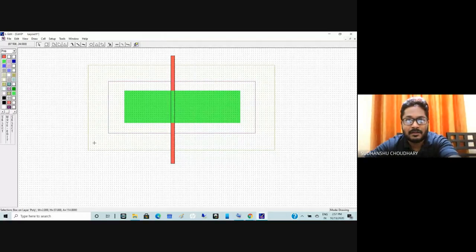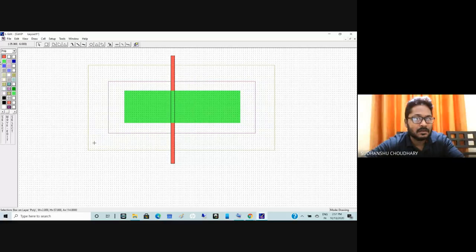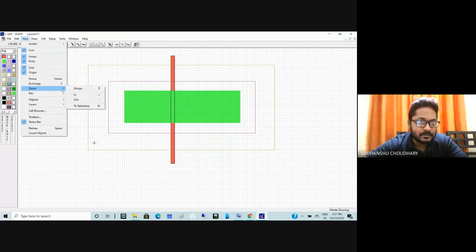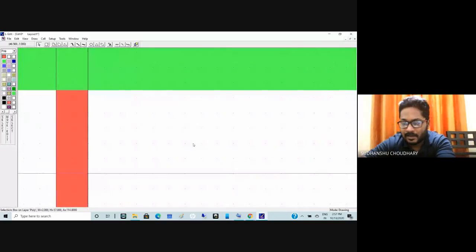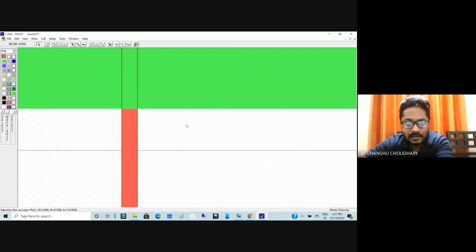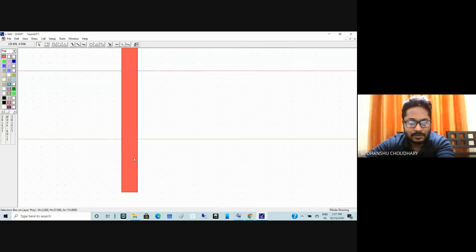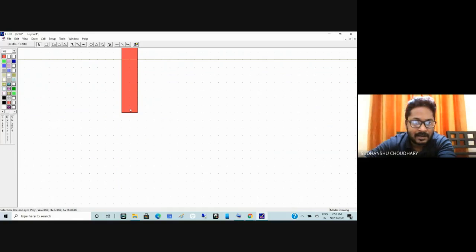Again, we specified lambda in the previous lecture, how you set this lambda. Lambda is actually the spacing between the 2 dots, right? So that is lambda. Spacing between these 3 dots, from here to here, that is 2 lambda. That is the channel length, right? So currently my gate length or channel length is 2 lambda. The minimum and even the maximum permitted is 2 lambda, right? So this is 2 lambda, the channel length.